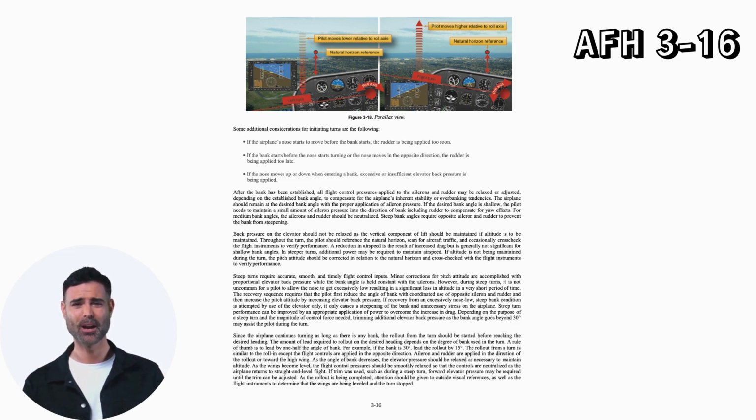Steep turns require accurate, smooth, and timely flight control inputs. Minor corrections for pitch attitude are accomplished with proportional elevator back pressure while the bank angle is held constant with the ailerons. However, during steep turns, it is not uncommon for a pilot to allow the nose to get excessively low, resulting in a significant loss in altitude in a very short period of time.